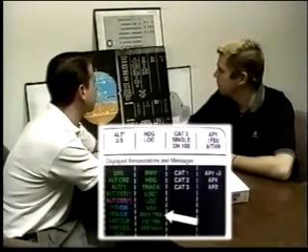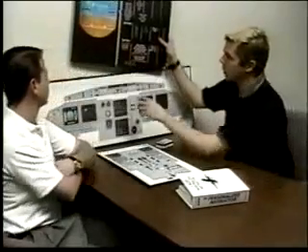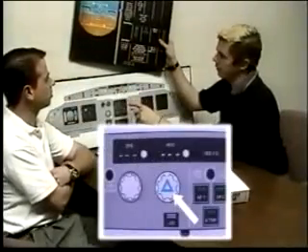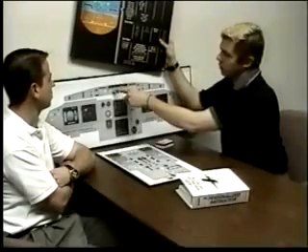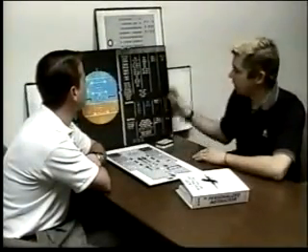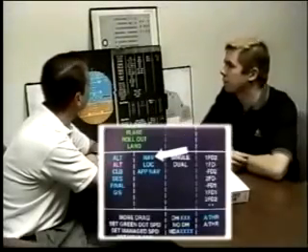after 30 feet, it memorizes the path that we took along the runway, and then it presents us with a flight director display to maintain that extended line. Runway track's available on all runways, regardless of whether or not it has a localizer. The only time we won't see runway track is if we forget to, or intentionally don't, set a heading in here during our pre-flight. If we select runway heading or whatever our first turnout's going to be, we're basically de-arming nav. If I didn't de-arm nav, not only would I not have a heading in here, but I'd also have a blue NAV on the second line.